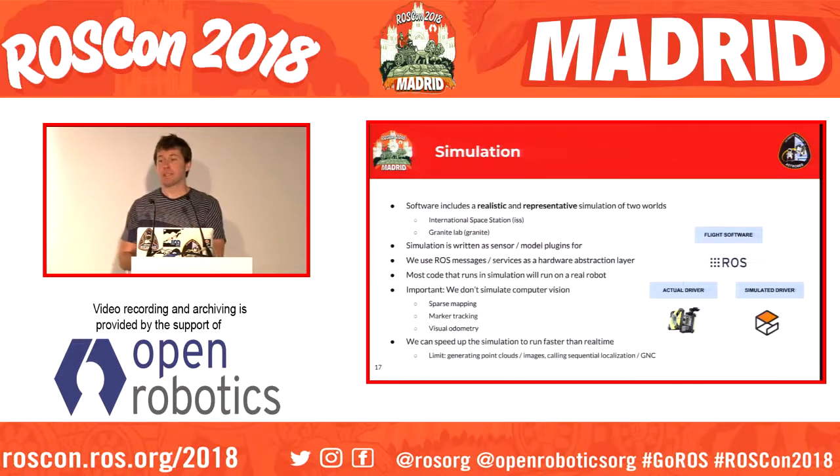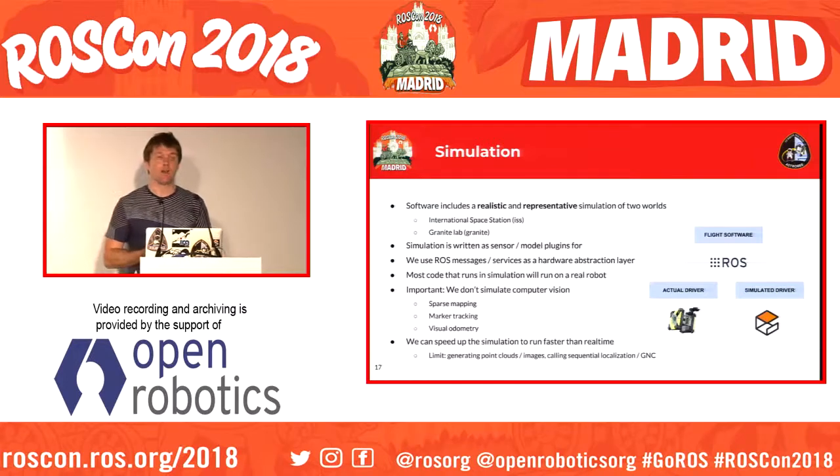A big test environment, though, and something we insist all of our project partners do before they get into working with us, is testing in simulation. The takeaway point with simulation is that we've tried to design our system such that we can divide our nodes into hardware drivers and flight software drivers, and transitioning from experiments to simulation is just as simple as switching out the hardware drivers. The only exception to this is that we don't actually simulate any feature detectors on synthetic images, because we feel that's a bit high in complexity and also probably doesn't add much value.